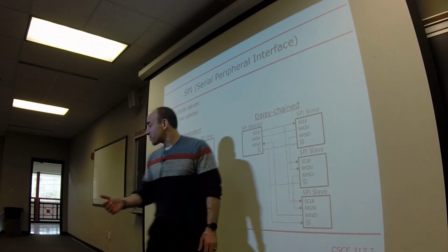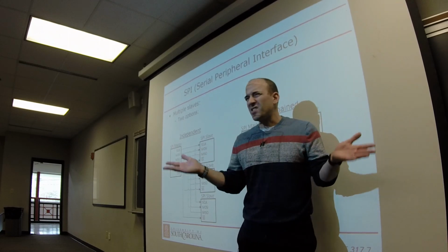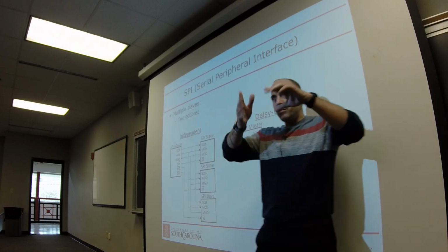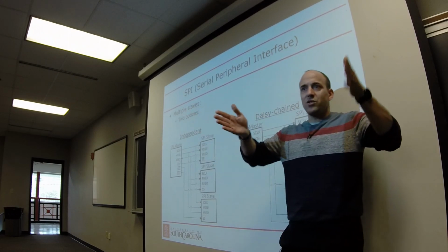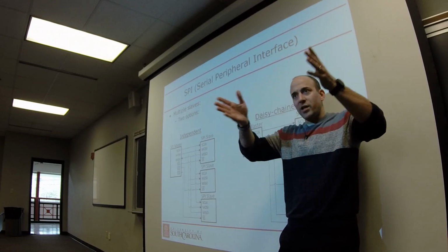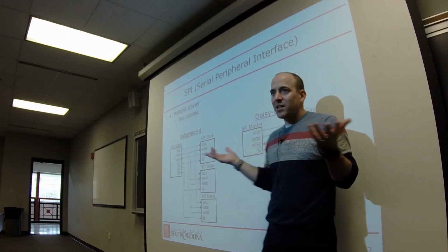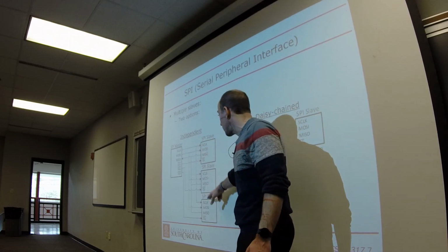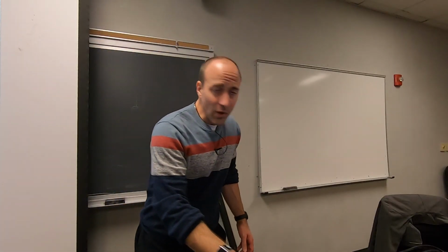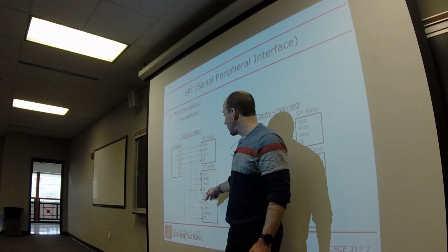Right? And I think that's probably why, because remember I said when you drop slave select in the accelerometer case, it's almost redundant. Like, who cares? It doesn't really do much except demark a one register transaction. Since you have to do multiple SPI shifts, it just shows you that you're doing operations that are part of a group of transactions to do a read or write, right? But other than that, it doesn't really do much. But in this case, it would be necessary to avoid double driving MISO. MOSI is not a problem because you're just fanning MOSI out to all of them. They all see the same MOSI. But MISO is the issue there.